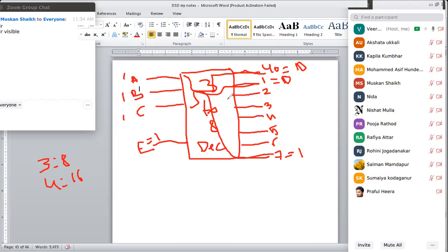So for this also, as we have written the Boolean expressions for the 2:4 decoder and implemented the 2:4 decoder in terms of AND gates, the same way we are going to implement the 3:8 decoder as well as the 4:16 decoder. Now directly we are getting non-inverted outputs. As we have A, B and C non-inverted inputs, we will have non-inverted outputs.